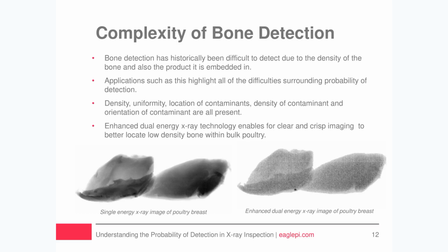With enhanced dual energy technology and image analysis software, we are capable of interpreting different views simultaneously. In applications such as poultry, we typically analyze 3 views per image. This allows us to fine-tune the software along with the operators used to specifically target certain types of contaminants. The example above shows the advanced material filter on the right-hand side, which is specifically used to target low-density contaminants such as bone, low mineral glass, and aluminium.